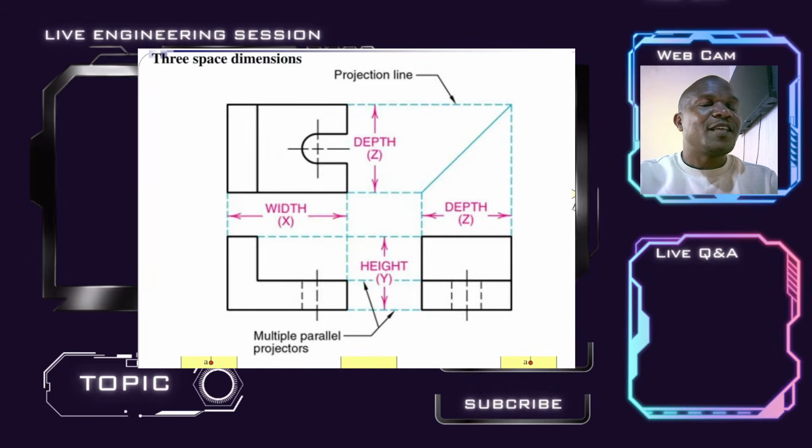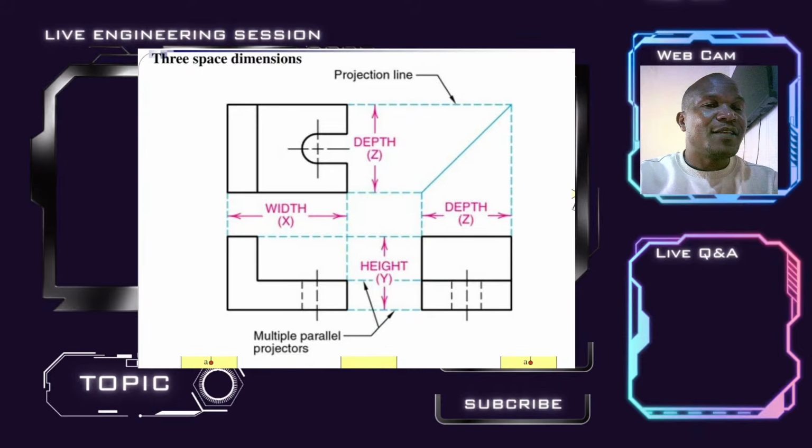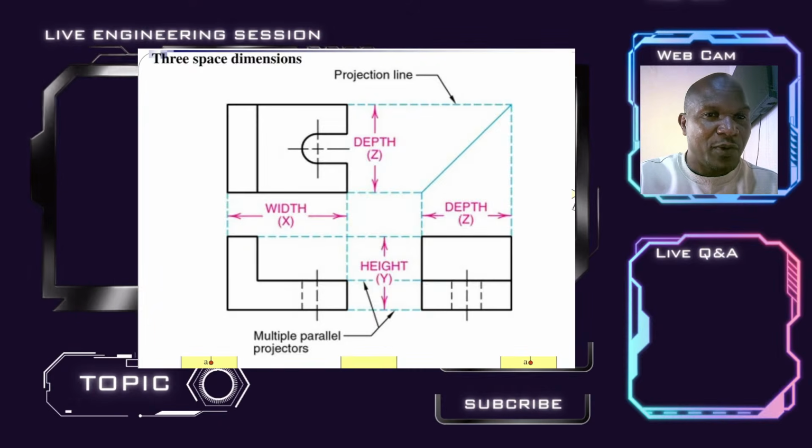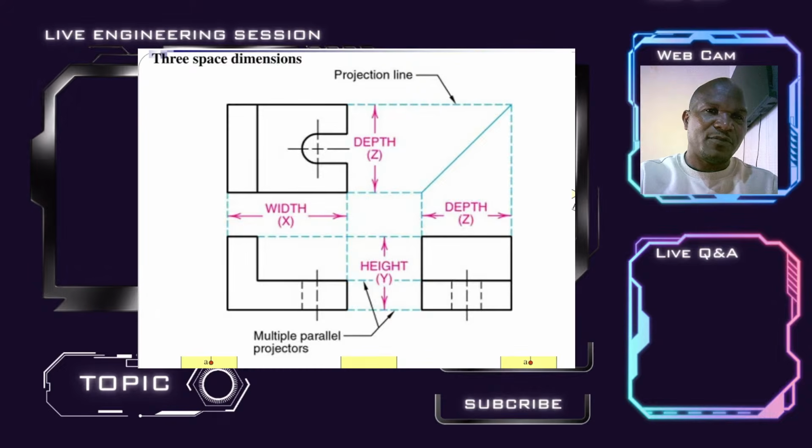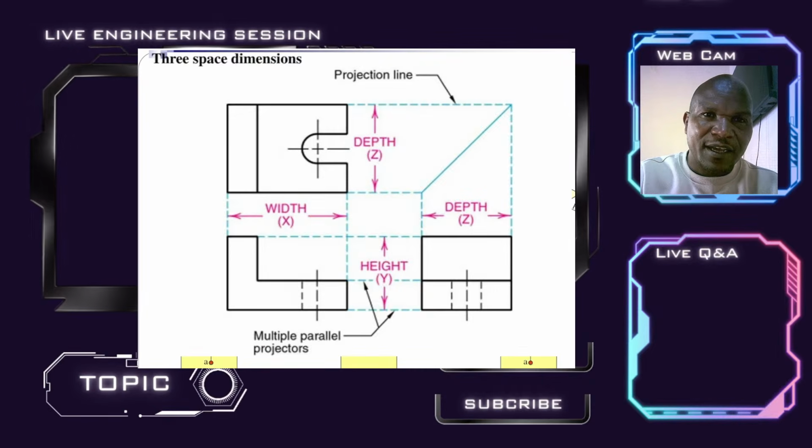Now, some of these edges are symmetric about a given point, and they coincide with one another. And upon completion, the side view is just a projection of the same lines extended. When we extend, we convert the same length from the plans also downwards onto the depth Z, converted at 45 degrees, and then orthographically, perpendicularly at 90 degrees downwards, we get the depth Z.